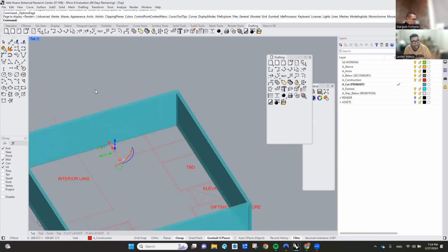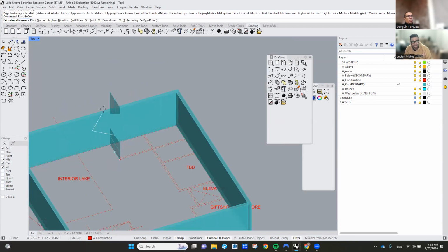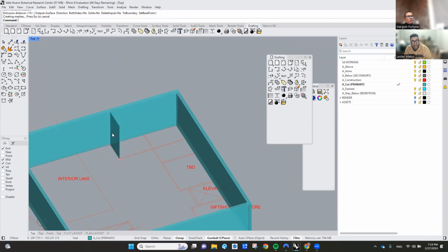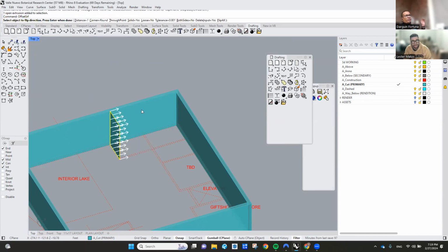So we're very quick. You already know how to extrude a curve. You can extrude that curve and select a corner of this element to know how tall. You can say offset and then offset curve, offset surface. In this case, after you've already extruded it, it becomes a surface or a poly surface. When it's just one flat face, it's a surface. When it has all of these dimensionality elements, it becomes a poly surface. All right, so that's that.